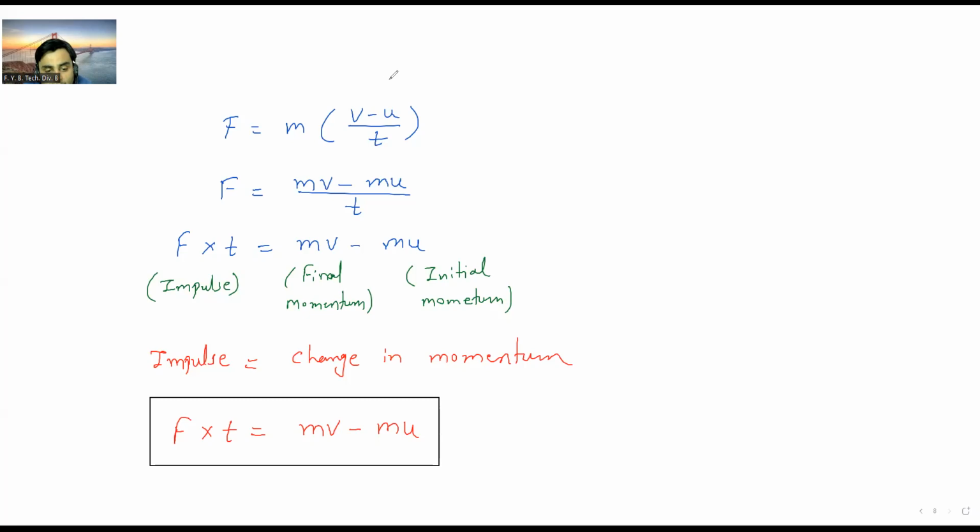So here how to take plus and minus. Here also F means it is summation F. Remember this. You should consider all the forces which are in that motion, in the direction of the motion. So here you can see summation F into T. So write down the sign conventions: when to take the force positive and when it will be taken as negative.